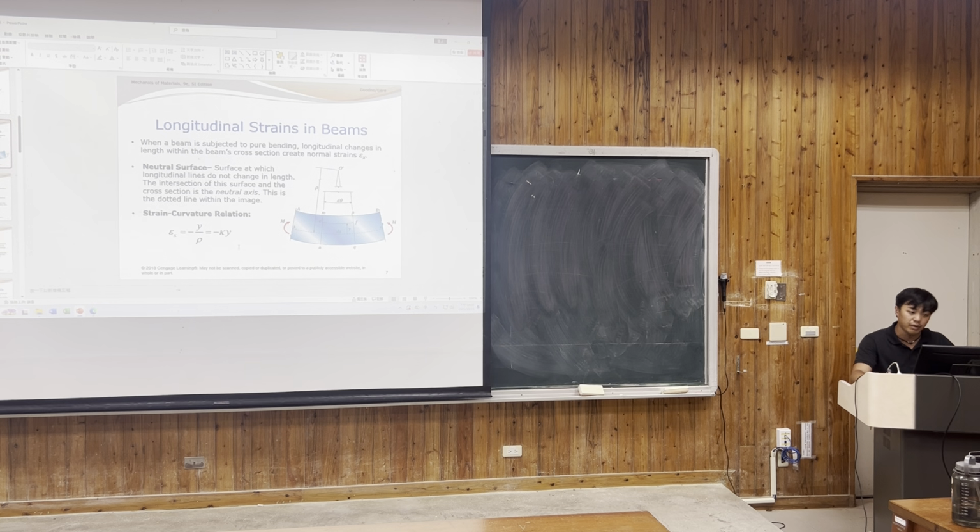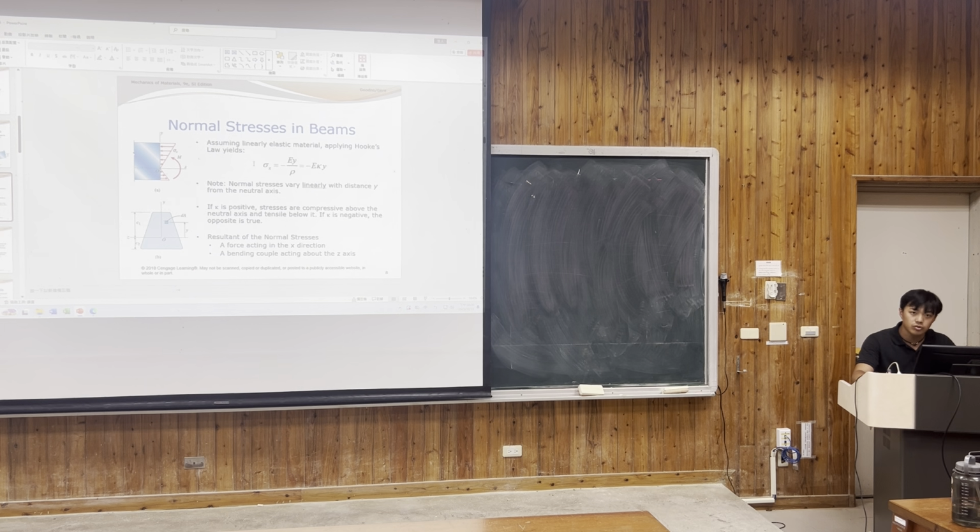So we got strain right here. When we multiply by E, Young's modulus, it will equal stress. So far so good? This is a part where you think it's easy, but you have to keep it in mind through the whole chapter, because it will be the basic concept of every calculation.